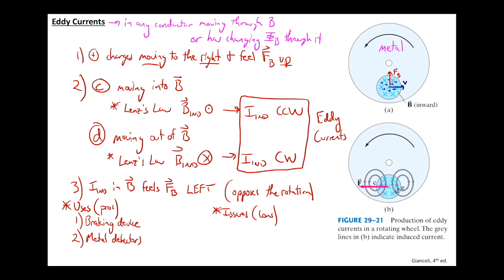And with the magnetic field that's being generated being turned on and off, it takes a second for those eddy currents to stop again. So there's a bit of a delay. So you can imagine magnetic field comes on, creates the eddy current, and then during the off state, it's making a measurement, making a reading.